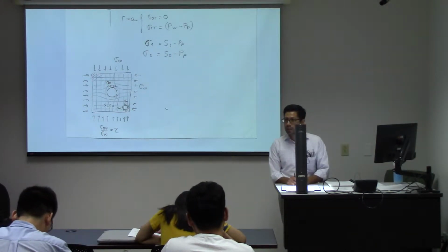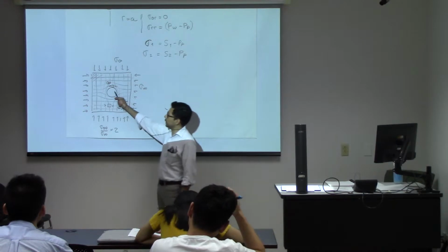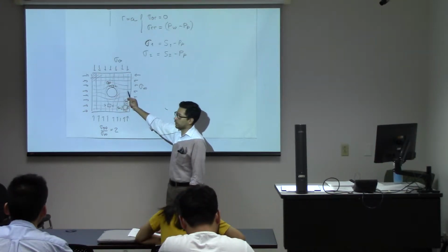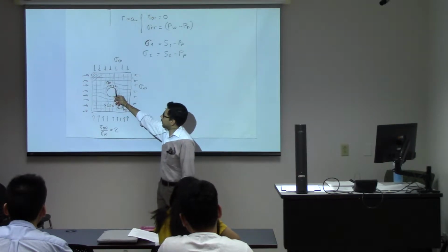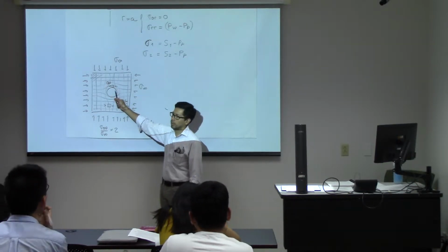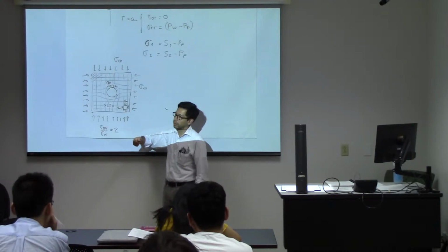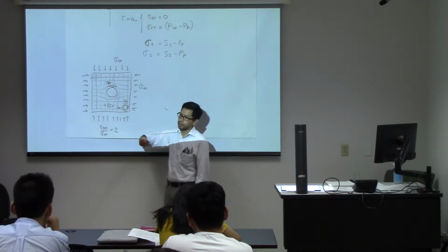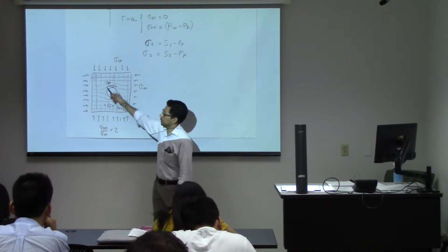And in radial stress, there's going to be no normal stress, right? So for example, if you want to drill a wellbore here and you have this made out of sand, and you have here no radial stress and no effective radial stress and some finite effective hoop stress, that will fail the rock. So because of that, you cannot drill a wellbore in dry sand, or even with sand where there is no effective stress in that direction.